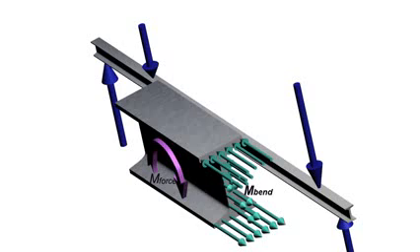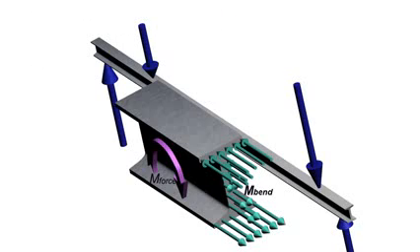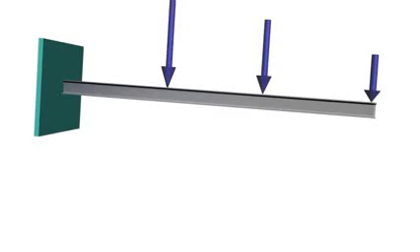Sign convention of bending moment is as follows. So we can calculate moment induced at any cross-section by balancing the external moment acting on the free body diagram. With these concepts developed, we can easily calculate distribution of shear force and bending moment along the length of the beam. We will see some examples.